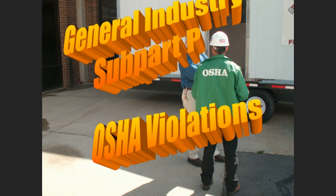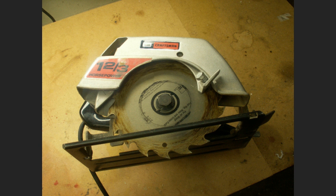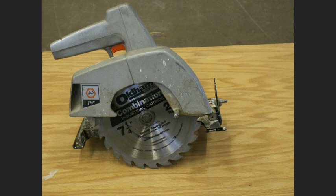And to kind of drive home our discussion on hand and power tools as we wrap up this discussion and training session, let's look at some common OSHA violations that I frequently see amongst all industries. Here we have a Craftsman circular saw, and the guard has been basically rigged up with a bolt so that it remains unguarded. Again, we see an unguarded circular saw.